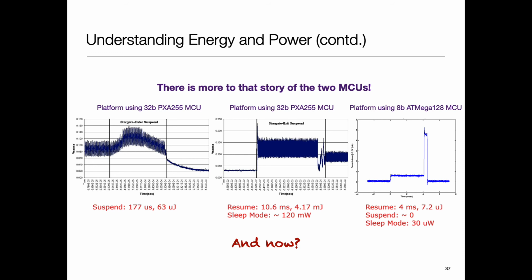Low-end microcontrollers nowadays, you can get microcontrollers whose sleep mode power is in picoamps or a fraction of a nanoamp. And they can get in and out very, very quickly. So now the whole story becomes even more complicated. If you're designing a system, what should you do?